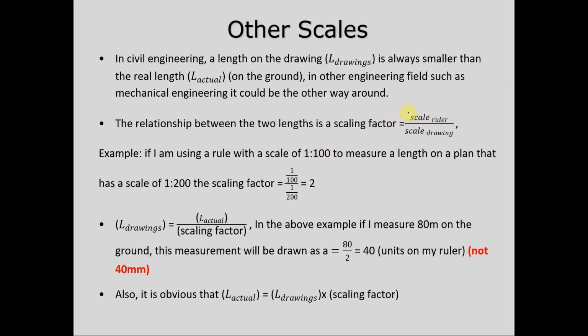That's why I was saying a minute ago, do not worry too much about the previous one, do not look at that rule. Let's focus on this particular rule here. This is our rule. This rule is saying the length on the drawing equals the actual length on site, divided by a scaling factor.